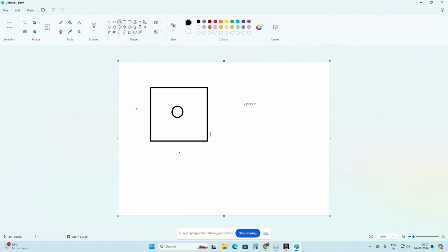So based on the parameter you define, this is what we are going to do in static structural analysis. In the problem statement, I'm taking a plate with a hole. For the dimensions, the x dimension is, for example, 50 mm, and this is also 50 mm. As of now I'm taking the thickness as 1 mm.